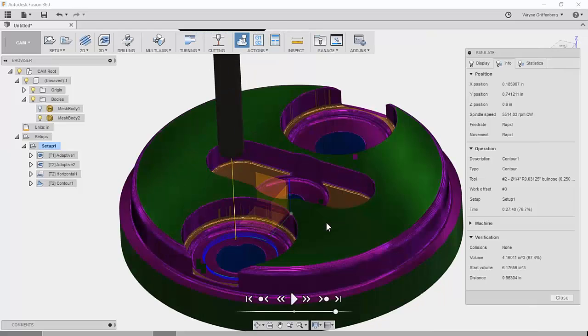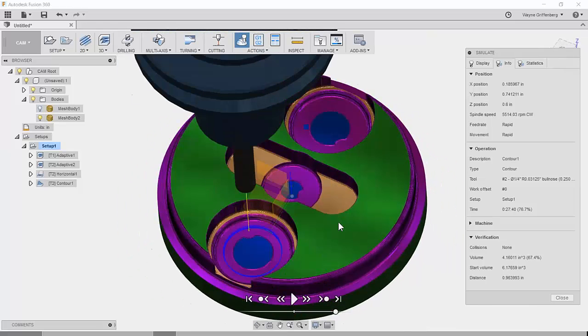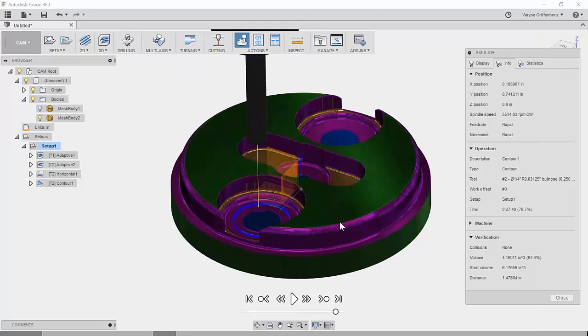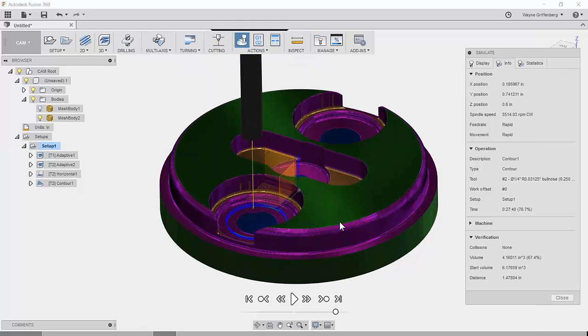So that's the result. Maybe we should be, in the vein of full transparency, with the exception of the facing toolpath, there is a reason Wayne is using the 3D toolpaths. The 2D toolpaths require chain selections, don't really work on STL files. So I just want to make sure we're transparent about that.